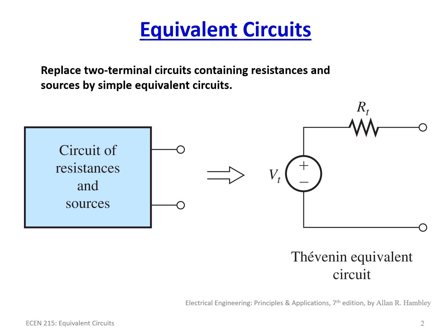If you're simulating those stages and doing an analysis on them, it's nice to break them up into a couple of mini circuits instead of one big circuit. Then you take the first part of the circuit, model it, turn it into this Thevenin equivalent, and use that to be the input for the second stage. You're actually going to see this used in a future lecture. So that's why we do this.